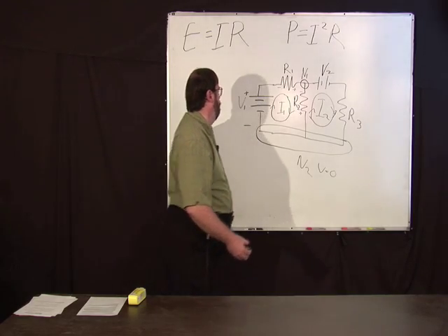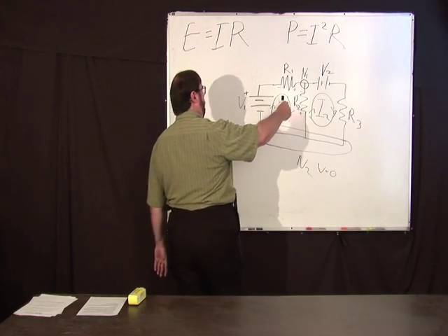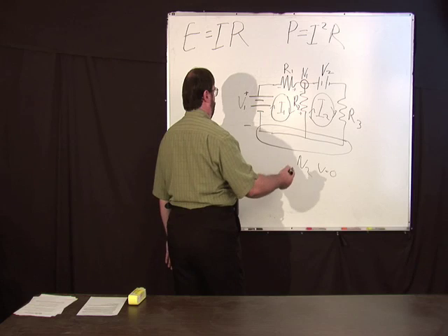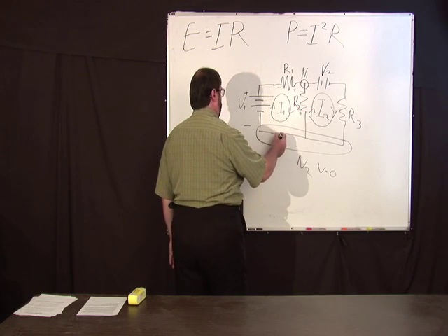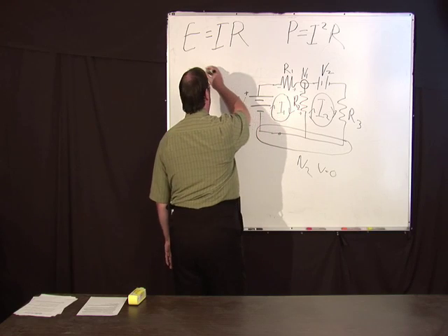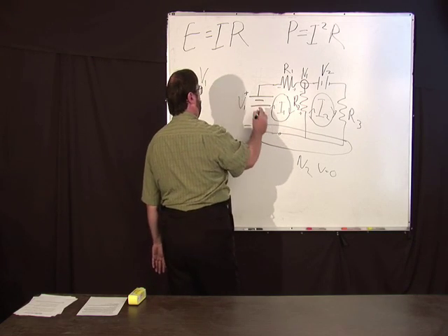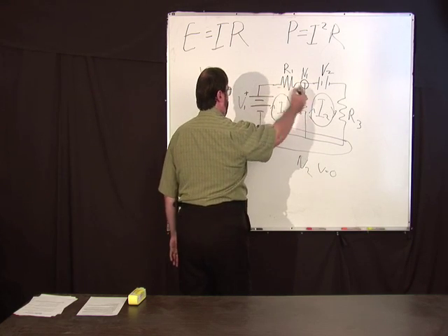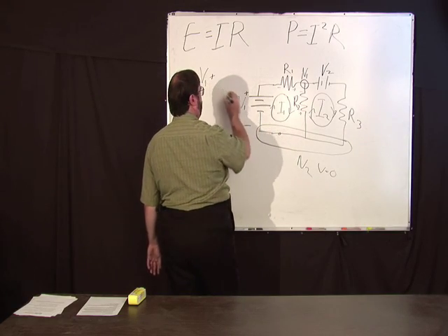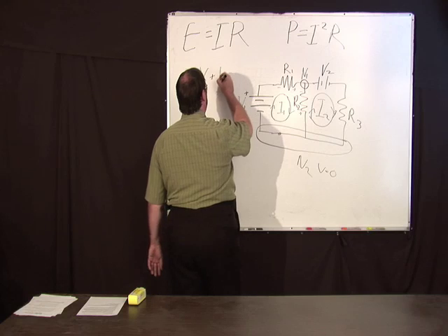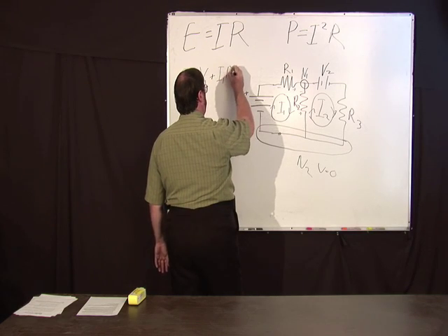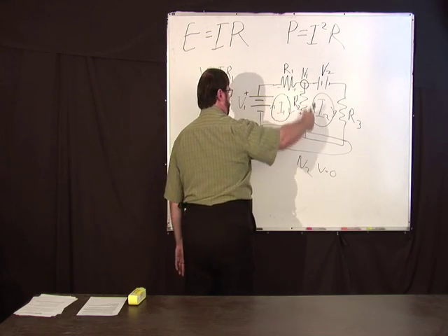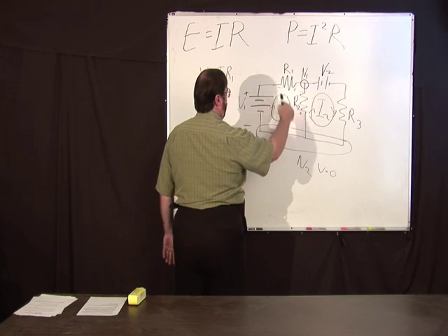Okay, so now you apply Kirchhoff's voltage law to the first loop, starting with here, I guess. And so we go, okay, we got V1, and then since this is plus minus, these are adding up, plus I1 R1, and then here, there's two currents going through this resistor relative to this one.